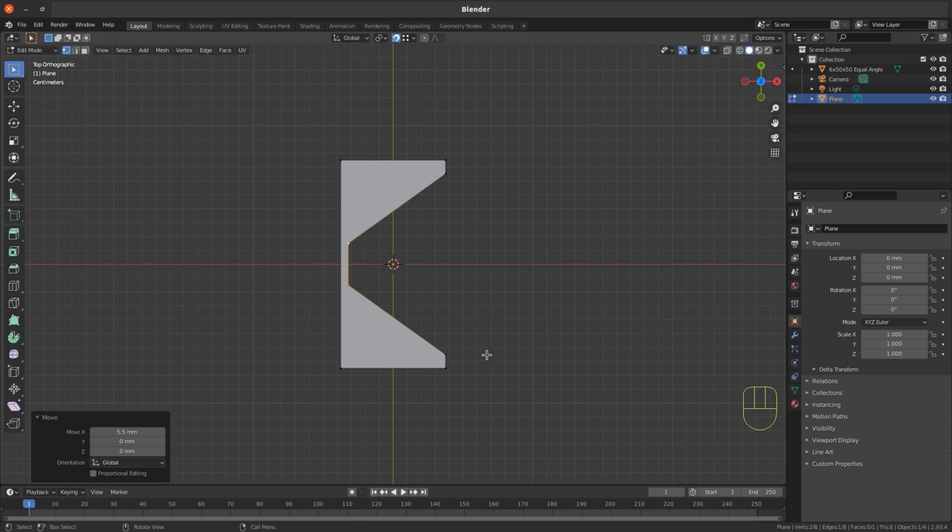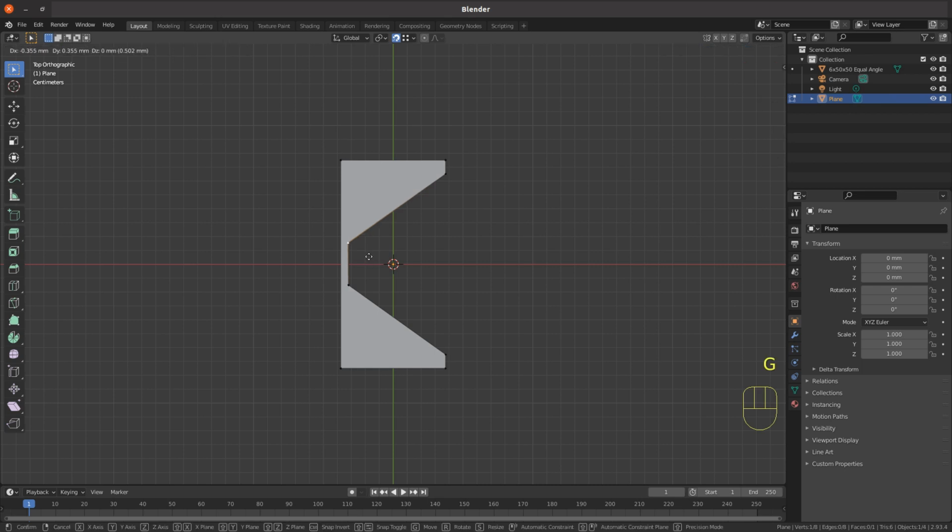and then enter. So all we have to do now is select each of them individually, and with the magnet snap them up to the inner vertex of the flange. So we'll grab the top of the 2 web vertices. So select the top of the 2 web vertices, grab it on the y axis and just move the mouse up to the vertex that represents the thickness of the top flange.